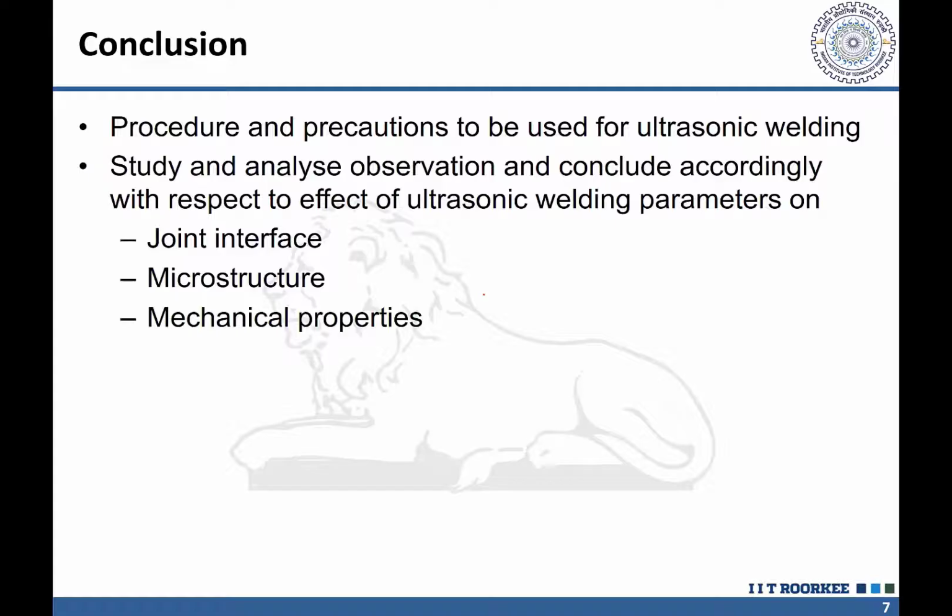So considering the various aspects related with the kind of thinning which is taking place, or the kind of interfacial bonding taking place, or the soundness of the joint, or the kind of metallurgical transformations which are occurring at the ultrasonic joint interfaces, or the load carrying capacity, the ultrasonic weld joint needs to be analyzed.